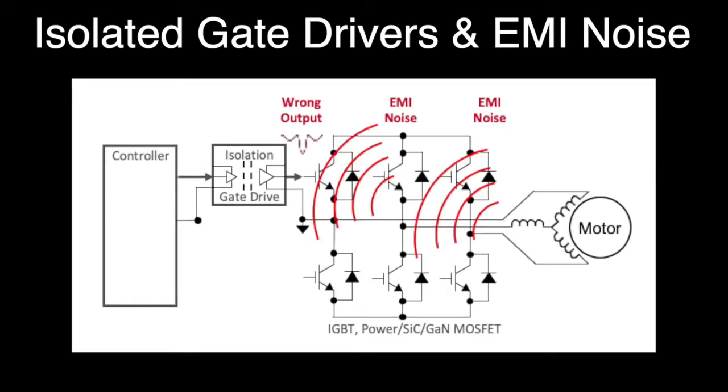In industrial applications like inverters and motor drives, EMI noise will be generated by an inductive load like a motor. The noise may cause reflection, resonance, or amplification within the gate drivers inside the power electronic equipment by its coupling through the wirings. This will cause the gate drivers to malfunction with erroneous output and, worse, be permanently damaged. To meet stringent requirements for functional safety in motor drives and inverters, it is very important for the gate drivers to be immune to the EMI noise.